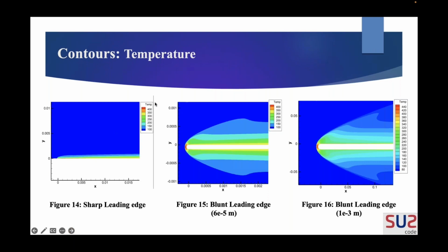Moving on to the temperature contours, here downstream of the shock, there is a significant increase in the temperature as well. Now we know that temperature and entropy are actually related to one another. So the entropy layer naturally comes into the picture. The entropy layer is a layer which deals with all the vortices. There is a point known as the entropy swallowing point.